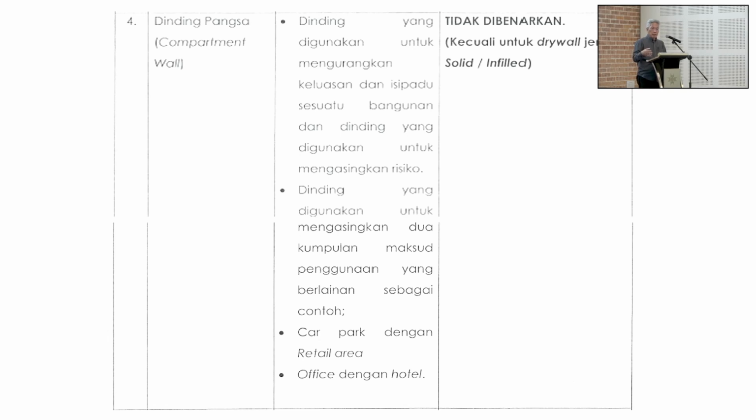So what they're saying is that if you build a compartment wall and it reaches the limit of the compartment volumes, then you'll have to come back and install whatever additional fire safety requirements when you reach the limits of the threshold on the 10th Schedule. Right? So they say to make it a little bit harder, but still allowing you to have future amendments or variations, they allow you to use drywall, but provided it's fully infill and solid.